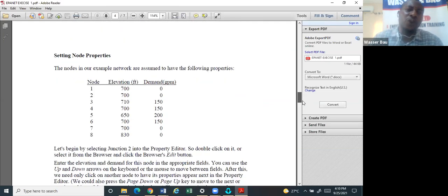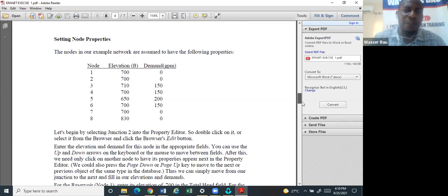After putting the 2 values for the node, we'll put the 2 values for the pipes, design our pump, design our tank, case is closed. 2 values for the node, 2 values for the length of the pipe. Then we'll design our tank with the elevation values of the tank, and design our reservoir. Design reservoir is only the total head. Then for the pump, we design a pump curve with the demand and then run our system. And that will be the end. It's very simple software. It's just for you to understand how it is used.